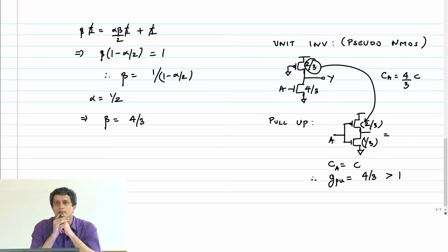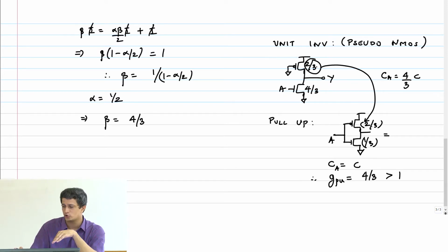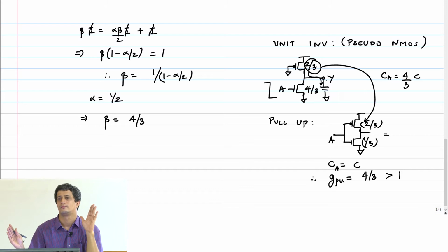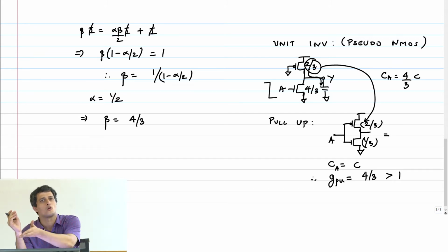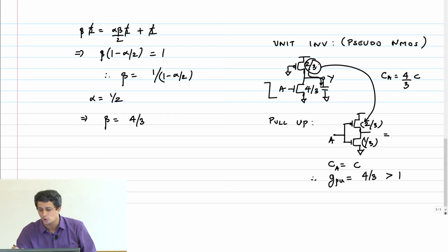Okay. So here there is no confusion because when the output is being pulled up, it means my input fell instantaneously and therefore the NMOS turned off. So all the current that is coming from the supply is flowing through like this. And therefore I said I can interchangeably talk about resistance and current here, because the same current is flowing through the load capacitor, no problem. So that 2/3 I replicated here, constructed the NMOS size and got the logical effort as 4/3.